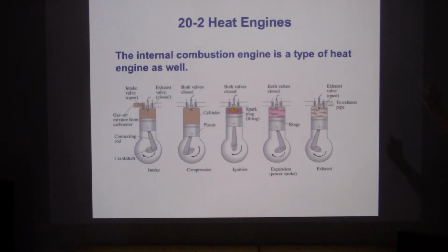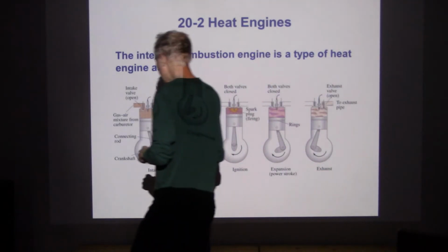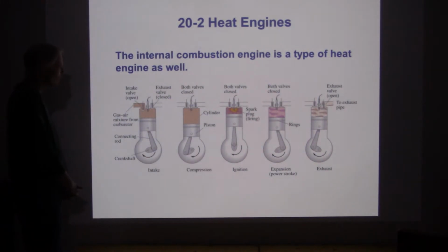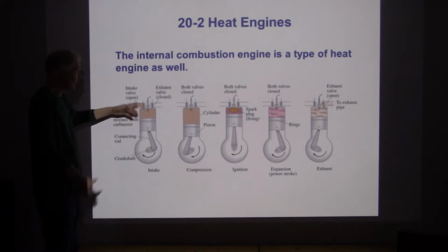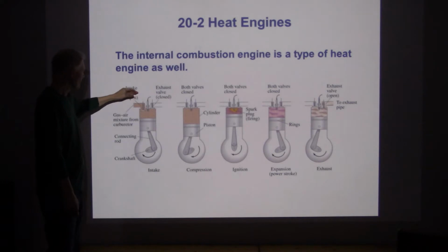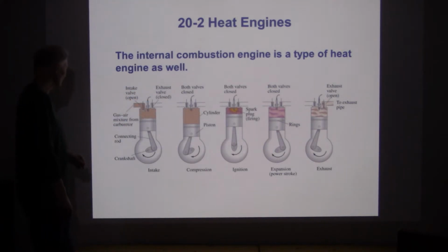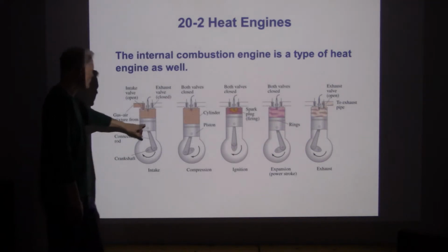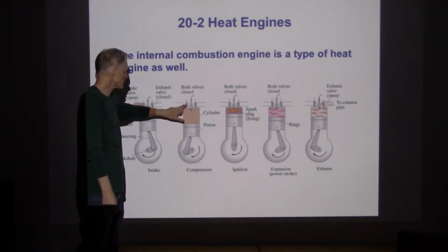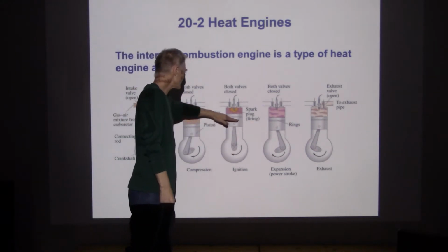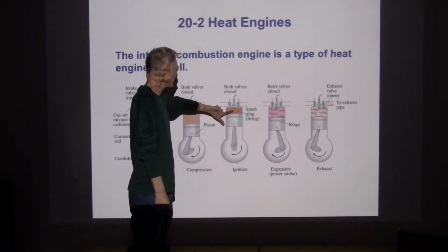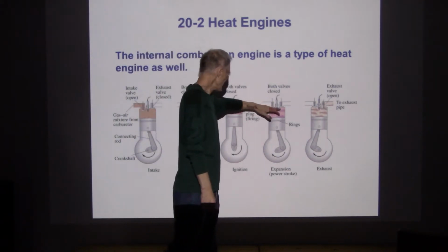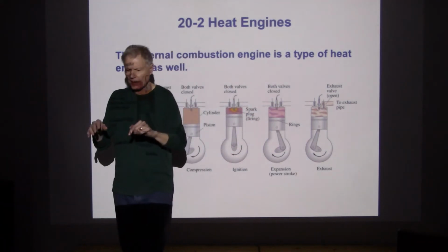Okay, back to the internal combustion engine. So here is what's operating still a majority of car engines, and so we're going to have an intake valve where a fuel-air mixture, gasoline and air with oxygen in it, enters a combustion chamber. Okay, so we're drawing it in. Here's the fuel inside, and now this closes. And then this is compressed, and when it's compressed at the top, there's an ignition that takes place. And that ignition drives the piston back very forcefully.